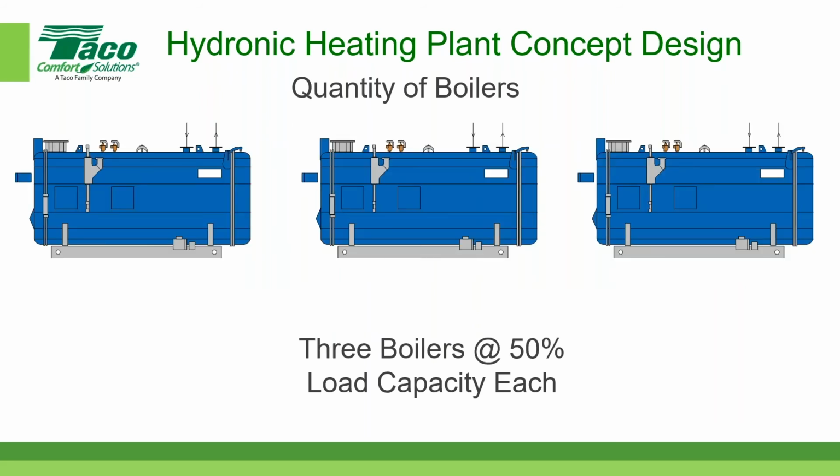Okay, let's look at the 3 boiler option. So one option is to have 3 boilers at 50%. That means if you lose one of the boilers, any 2 boilers would provide 100% of load capacity. And the other option for 3 boilers is 3 boilers at 33%. And the logic behind there is, yes, if you lose one of your boilers, then you only have 2/3 capacity,